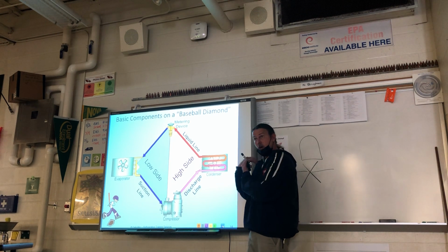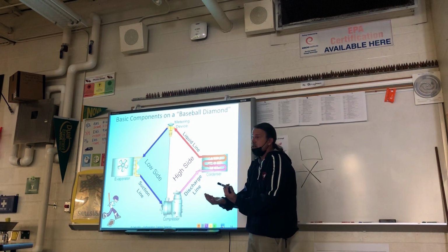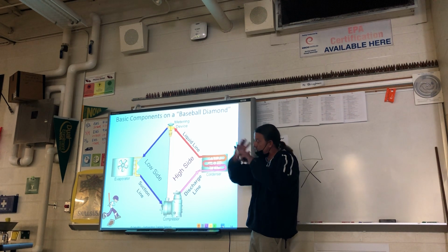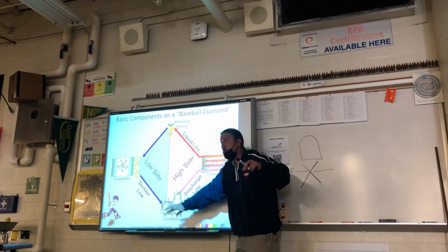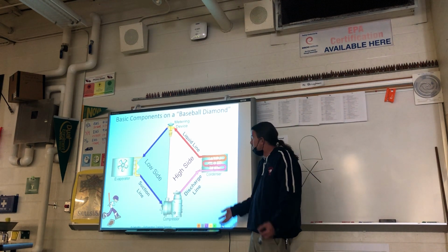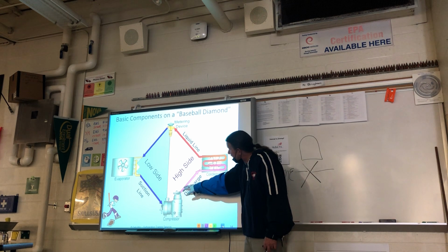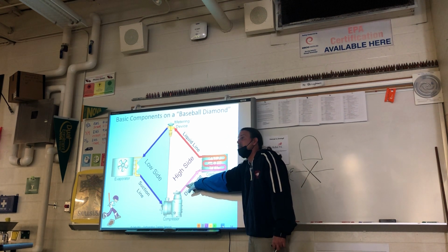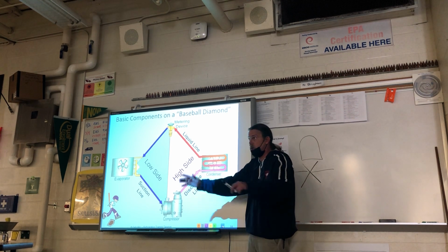Or you go out to Arizona, and they say it's a dry heat. And their units are different out there. They have a lot of evaporative coolers. They're using a completely different system than this cycle. But they have these cycles out there in Arizona because they do have rooms that need cooling. And if it gets 110 degrees outside, this line's going to get 210 degrees sometimes. It could go up to 300 degrees, which starts breaking down the oil.